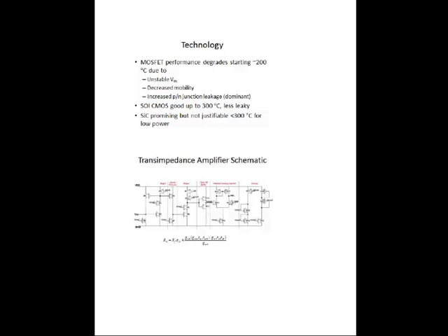Then we have an amplifier here that feeds back and sets this DC voltage to a reference voltage, which was set to VDD over 2 by an internal bias circuit. So this node stays at about Vref, and we use an external compensation capacitor for that loop.